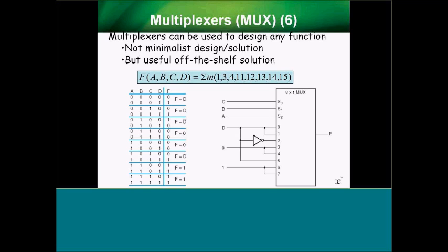But if you already have multiplexers, if you're using an 8x1 multiplexer and there's a couple of these on the chip and you have some spare ones to use, you might be able to just use one of those multiplexers that is not being used and implement the entire function with some other gates that you have, and therefore you don't have any extra chips, or 2 or 3, 4 more chips, depending on how complicated the circuit is. So it's an example of a problem. I'll show you some example problems I've given the students after this.